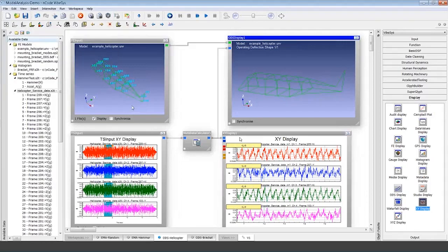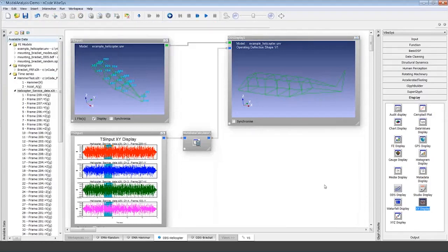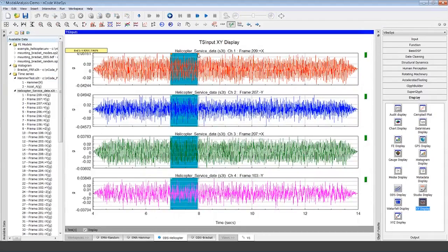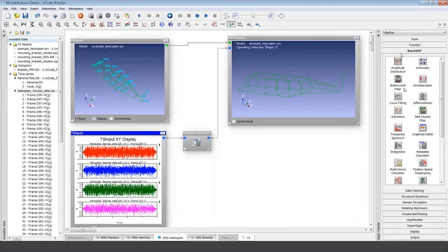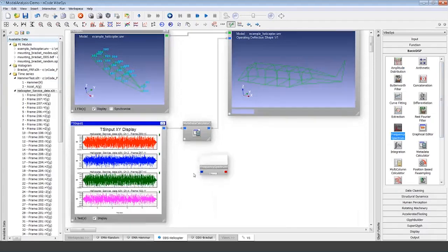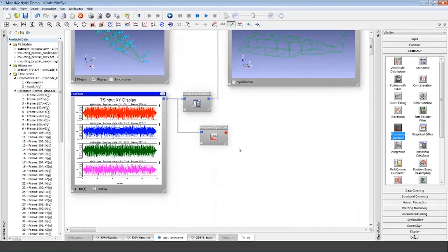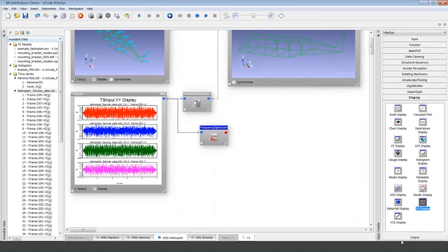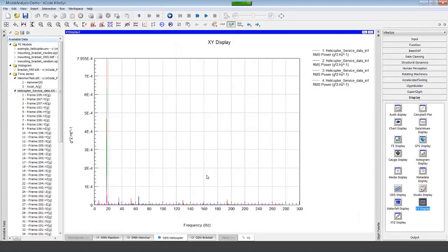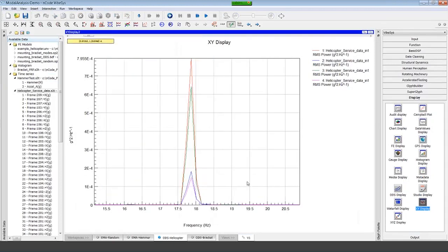So one idea is maybe to focus on one particular frequency. So what I suggest is let's have a look at the frequency content of those signals. Let me just grab, and you'll see, the basic DSP contains all sorts of interesting tools. One of them is the frequency spectrum glyph. So let's ask it to compute a spectrum to see the frequency content. And look at this. There is one frequency that clearly is much higher than the rest, and that's around 17.5, 18.